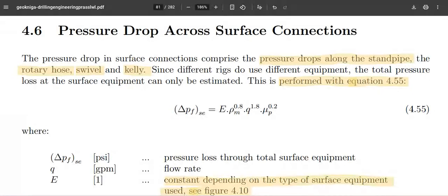In the last video, we saw how to compute pressure drop due to frictional loss in pipes and annuli. For laminar flow, we compute closed form analytical solutions. For turbulent flow, we compute this frictional loss by using some empirical correlations for both Newtonian and non-Newtonian fluid.